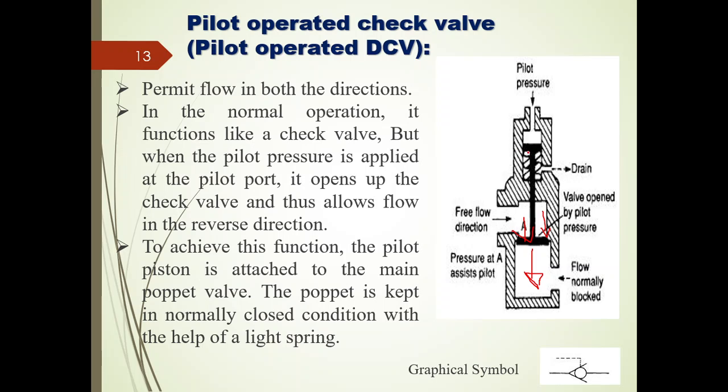So it is opposing the spring pressure whatever we have here, right? Because of that high pressure the piston will move downward, because of which when the piston reaches this particular point I'll have enough space to move the hydraulic fluid from A to B. But the reverse is not possible here, because already the larger piston whatever we have is seated in the seater.